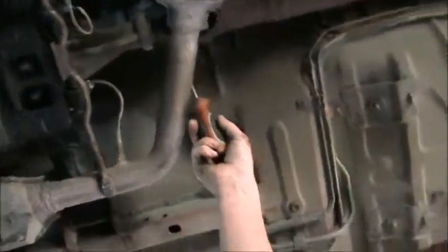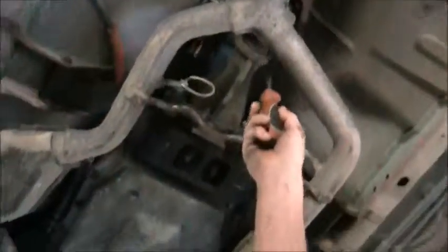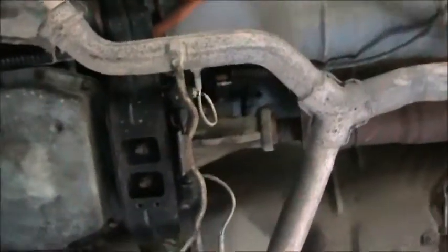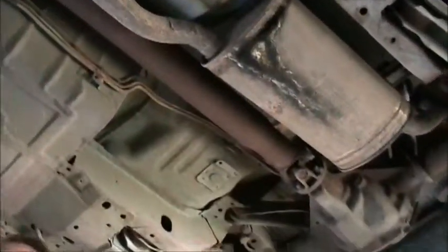Next we have a drive shaft. The drive shaft on this vehicle is one piece. It's not near as long as on the big truck, so we don't need to have a center carrier bearing. We do have a slip yoke in the front of the vehicle right here where it goes into the transmission. That allows the drive shaft to move in and out of the transmission to change lengths. Again, as the rear end moves up and down, the length of the drive shaft has to get longer or shorter. So we do have a slip yoke in the front.